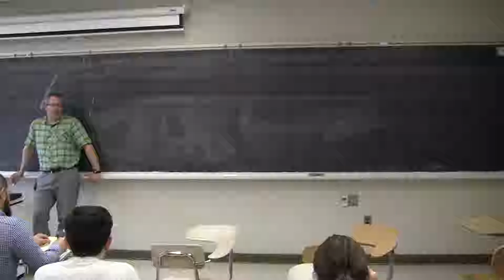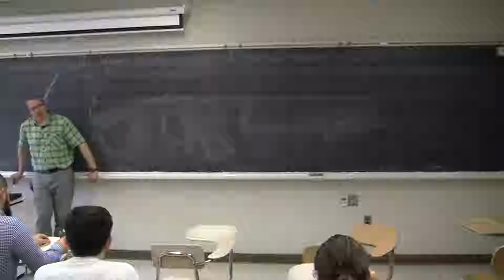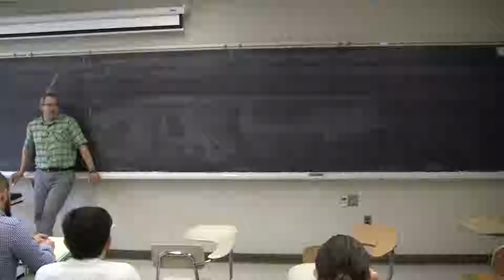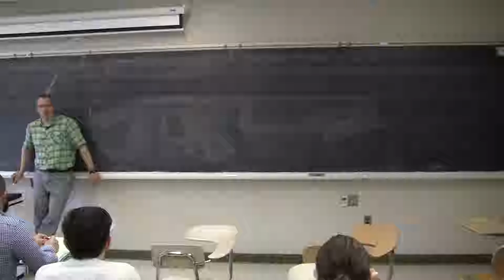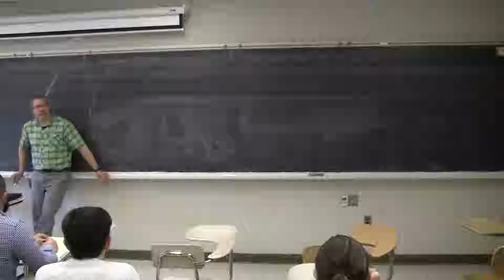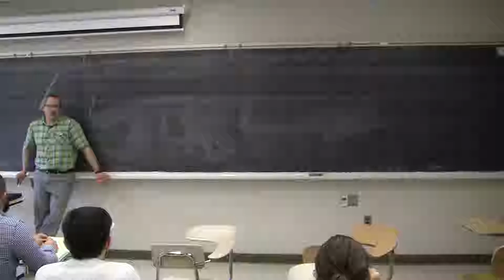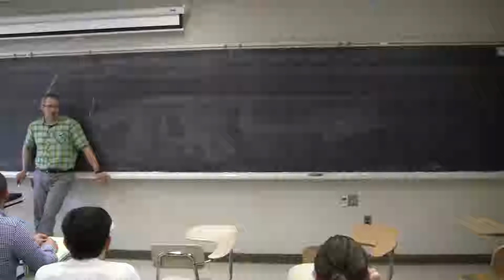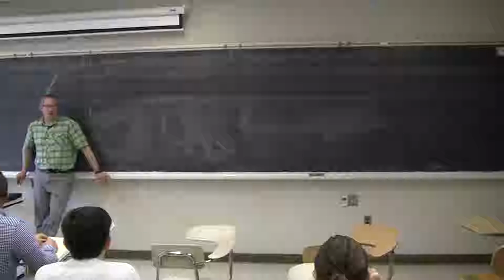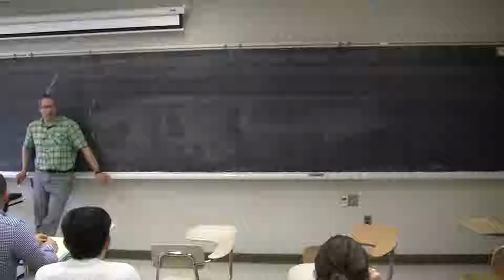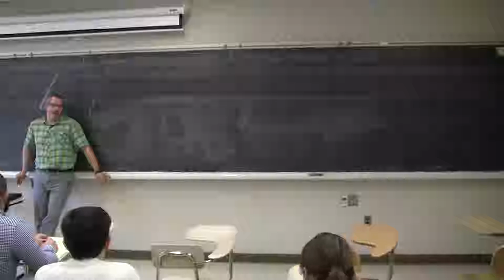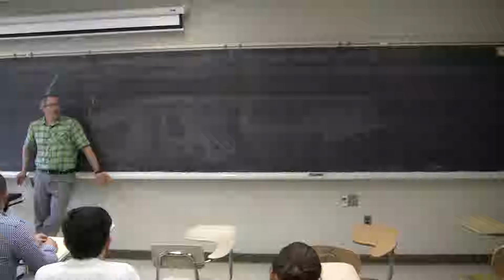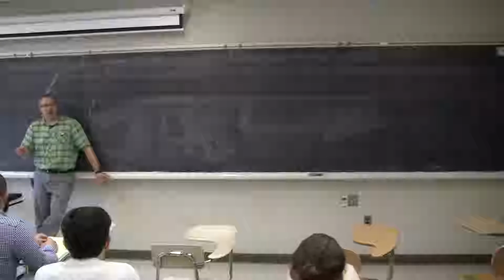We always had S equals V I conjugate, and the reason we need a conjugate is when you convert p(t), the instantaneous power, and that's the real power that you have. But in AC circuits land, we do things in steady state. So we have this real power that is being consumed or dissipated by the load, and then the reactive power is the one that goes out, sets up magnetic or electric fields, and then has to go back. It doesn't do any real work, okay? So that reactive power part is the part that we have to take into account.